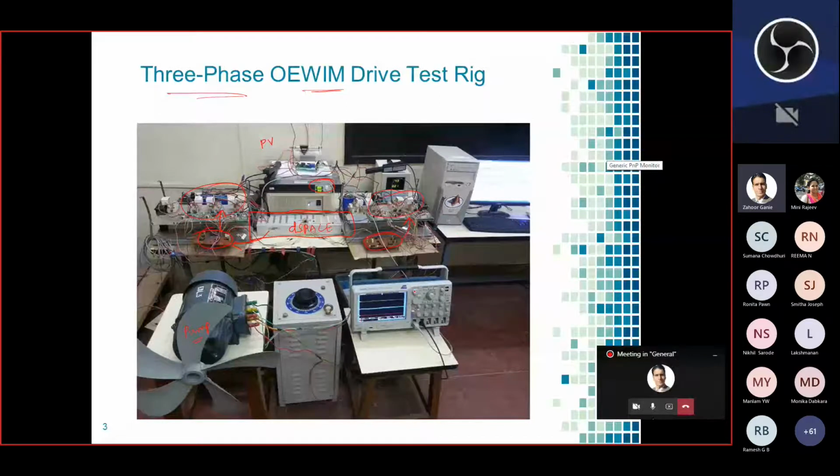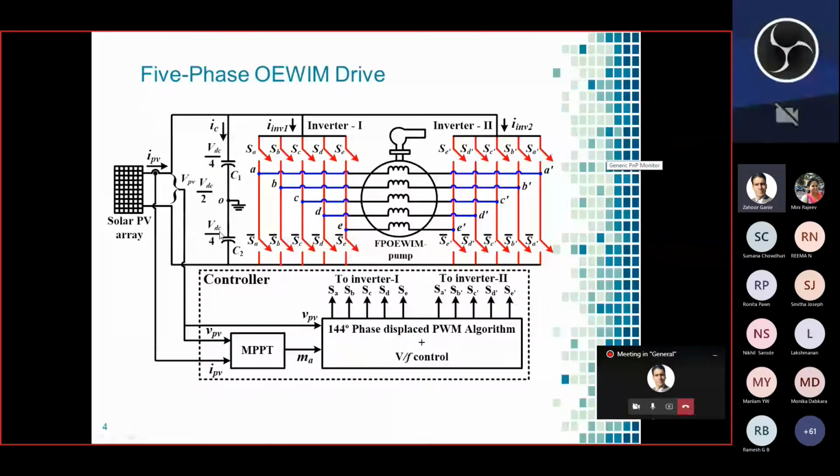That is fine, but we then tried to extend our work to a 5-phase machine. Not a simple 5-phase induction motor drive, but again a 5-phase open-end winding induction motor drive. We have mainly focused this application on electric vehicles. For electric vehicle applications, when we extend this 3-phase open-end winding concept to 5-phase, we should have some closed loop control, closed loop speed control. Maybe you may have DTC or PTC or MPC. There are many closed loop control schemes, and we may use any of them. So we just want to extend our work to this.